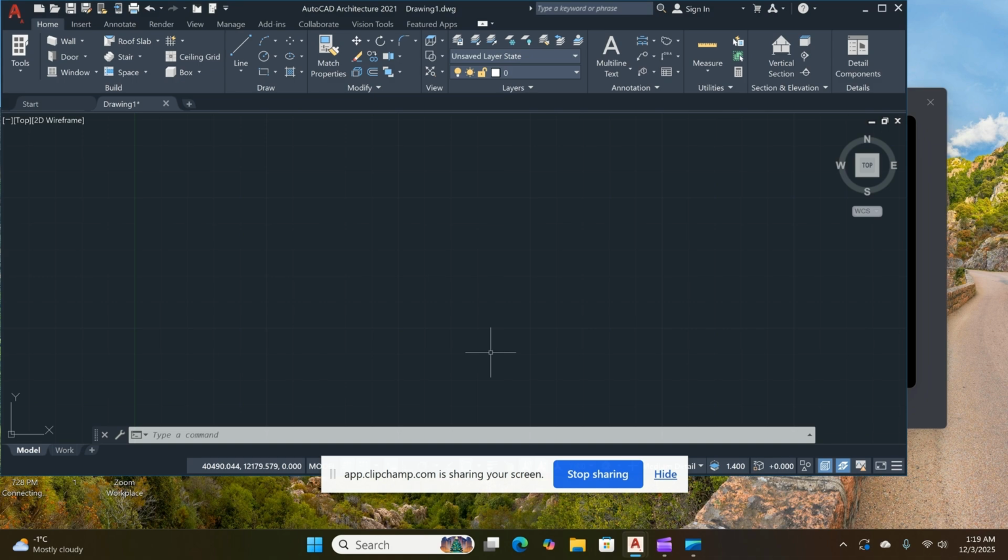I will now enter the first line segment followed by the second segment using the same method. Entering the first segment, the bearing is N29 degrees 53 minutes 45 seconds east, and the distance is 13.26 meters.